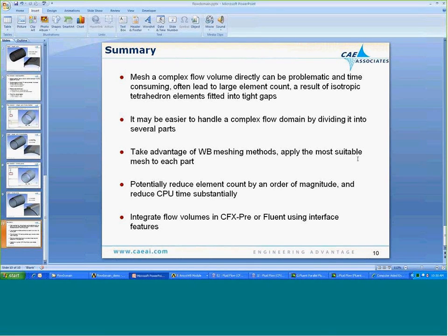So it would be ideal to have a flow-through mesh, obviously, but if you can't, try to create the interface mesh with roughly the same size, and then use the domain interface or mesh interface functions to integrate them together to help you with unsteady analysis or large problems with very large